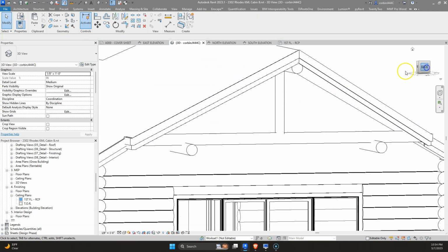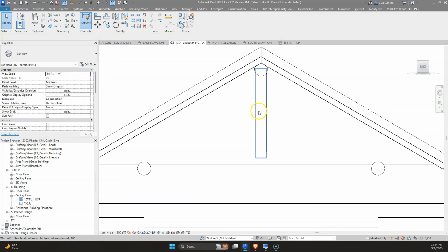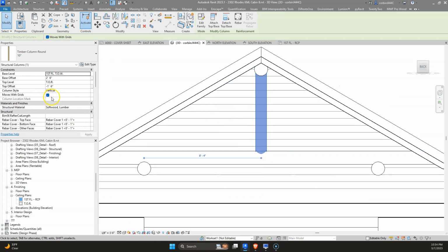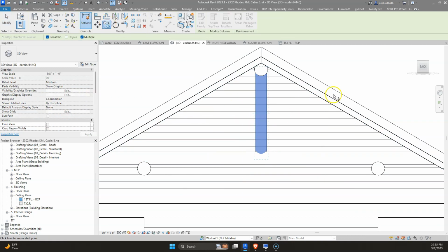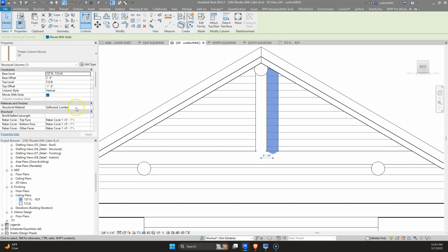And so here comes the next step. So we've got our column here, and next thing we want to do is we want to make the angle braces kind of in the side. So what I like to do is I like to take our column, and I'm just going to copy it over. Let's just say the width of our column. So let's copy it over 10 inches. I mean, obviously it's not the exact width.